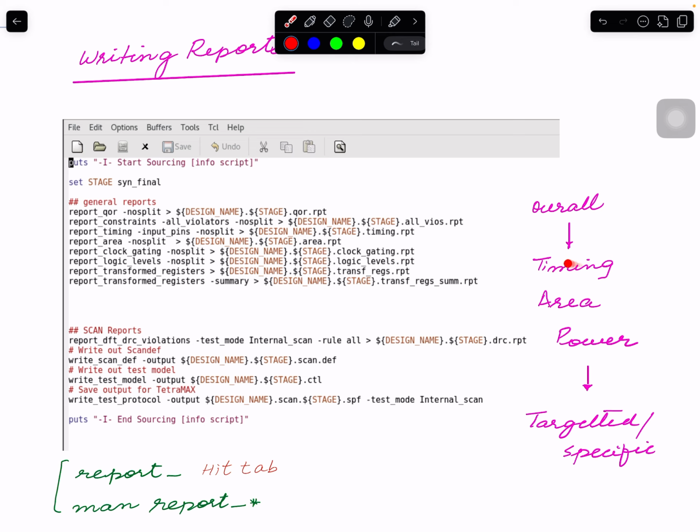Okay, so in the timing, the very first thing I want to see is, okay, my internal timing, whatever frequency I set for the clock, do I meet that or not? Simple as that. Okay, so yeah, I want to get some idea of that. Okay, if it's not, what's the worst negative slack? How many logic levels are in the critical path? Stuff like that.